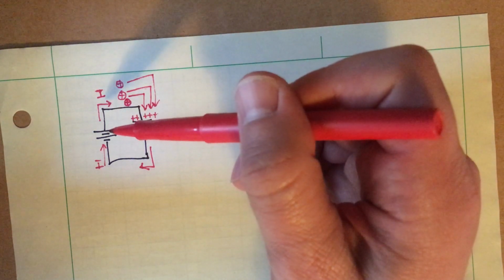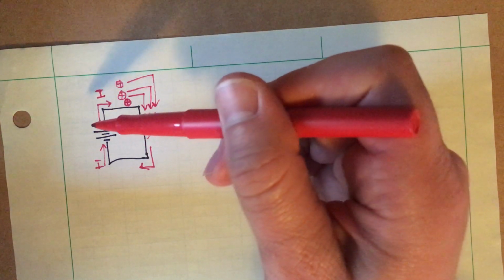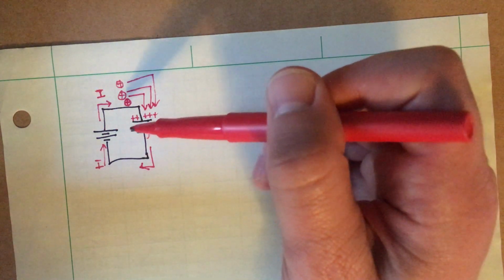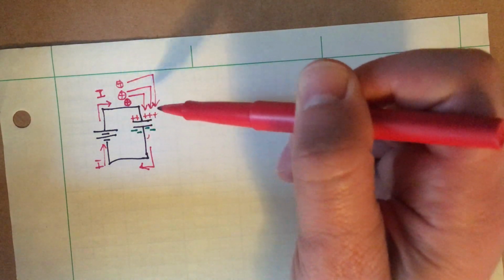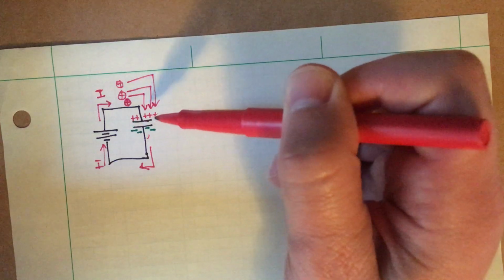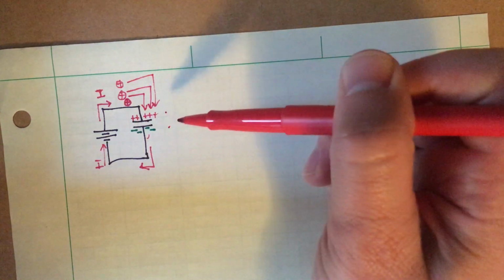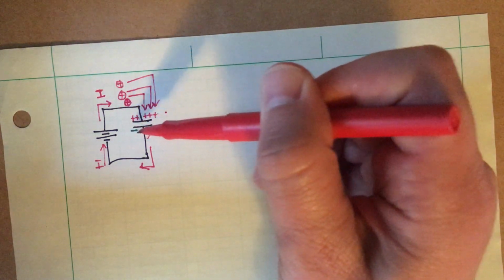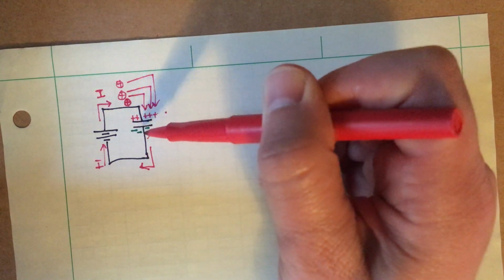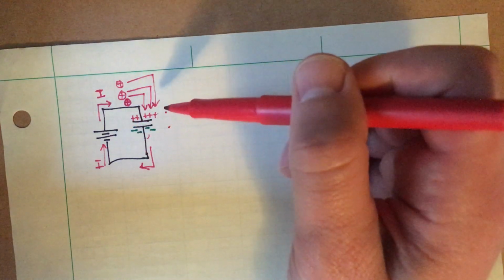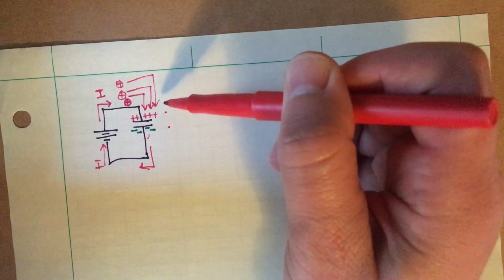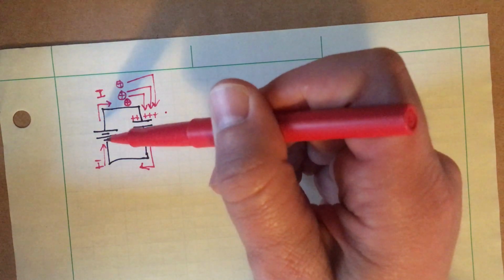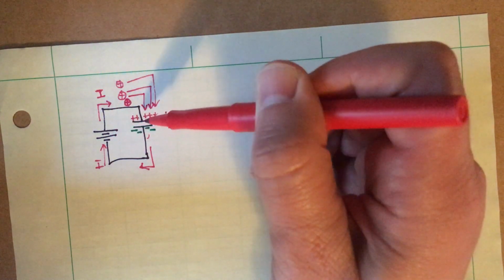Okay? In fact, if you look at the loop rule, what the loop rule tells you is that the voltage added to the circuit by the battery has to be equal to the voltage subtracted or working against the battery from the capacitor, because you can see that if you think about this as like a little battery, so you've got a positive and negative charge there, that if you shove enough positive charges onto this end, which means that an equal number of negative charges are left over here after you push the positive charges away to complete this thing, then you're going to have a voltage of the capacitor that's trying to push current the other way, right? Counterclockwise through the circuit, whereas the battery is trying to push it the other way. So it's like two batteries opposing each other in a circuit.